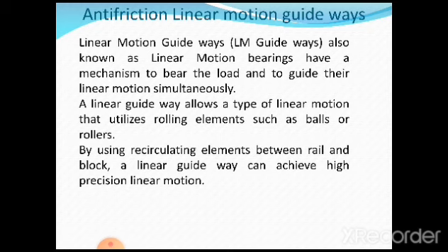Linear motion guideways, also known as linear motion bearings, act like our regular bearings. Whenever I want to rotate any shaft, I need to hold the shaft in bearings known as supports. In the bearings you have the inner race, an outer race, and a cage, and in the cage you have all the balls or the rollers which are used for taking the load of the rotating shaft. This is very, very important.